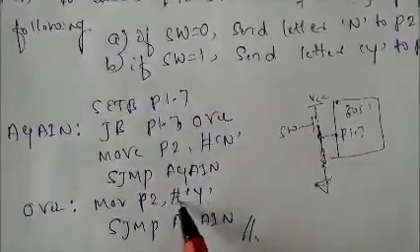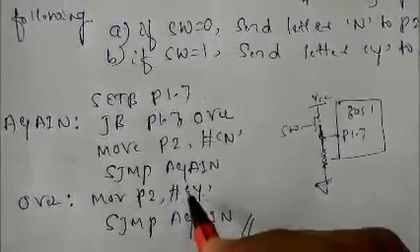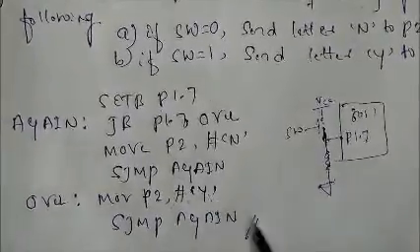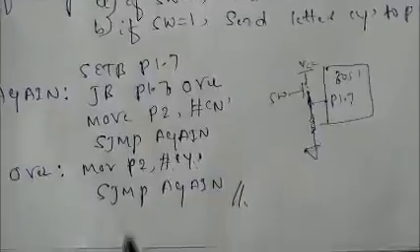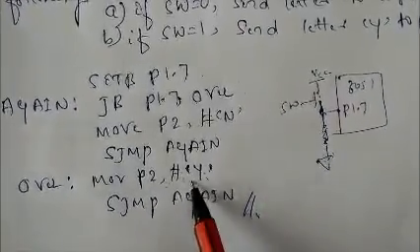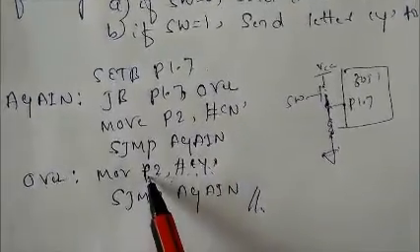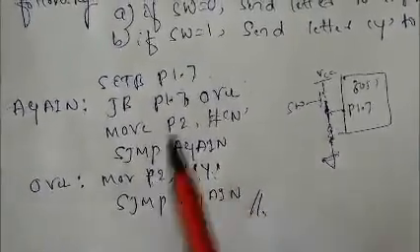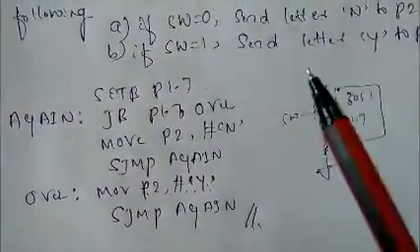So that means this way also we can transfer single characters. Is it clear? When you are going to write characters, it should be in single quotation marks. An individual single character needs to be represented with single quotation marks here. So what will happen? MOV P2, #'Y'. That means this single character will be sent to your P2 port when the switch equal to 1 condition is met.